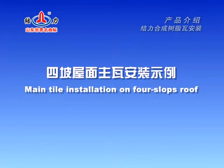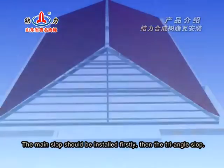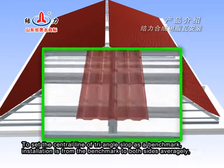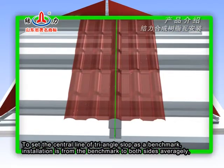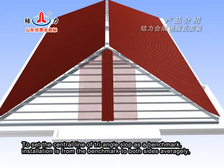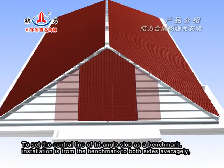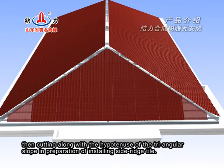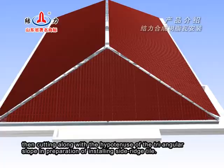Main tile installation on four slopes roof. The main slope should be installed firstly, then the triangle slope. To set the central line of triangle slope as a benchmark, installation is from the benchmark to both sides averagely, then cutting along with the hypotenuse of the triangular slope in preparation of installing side ridge tile.